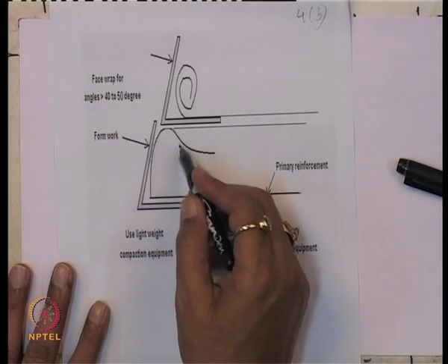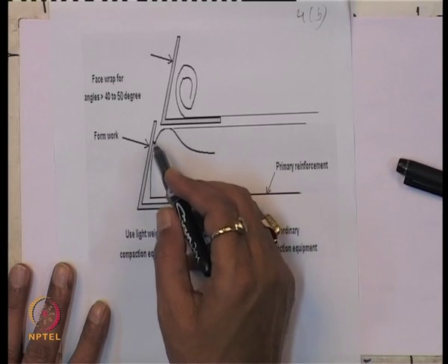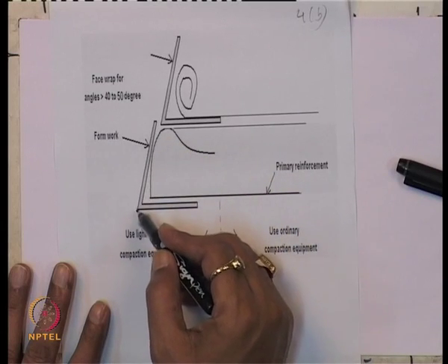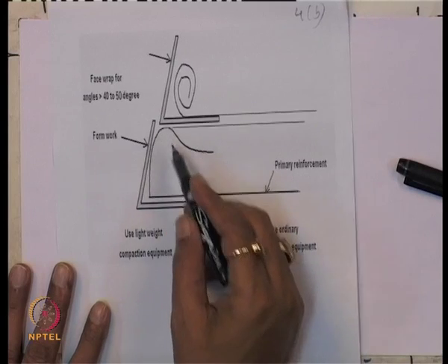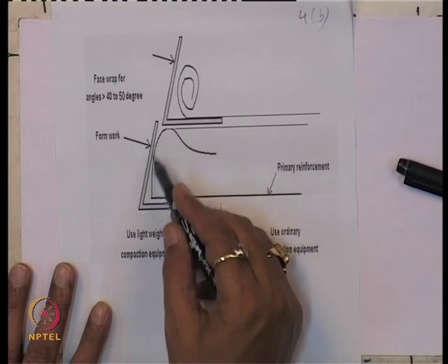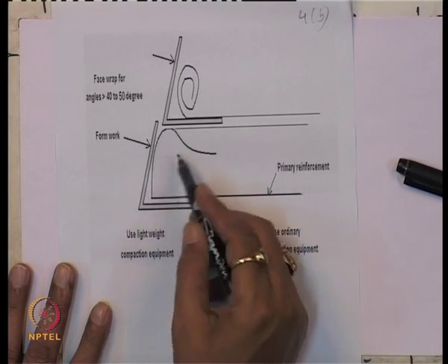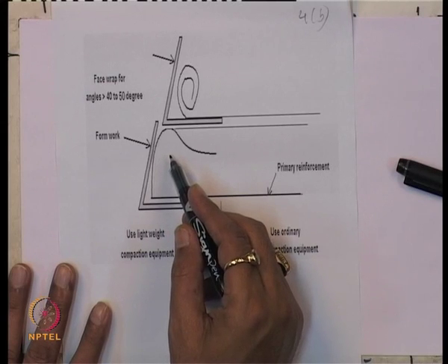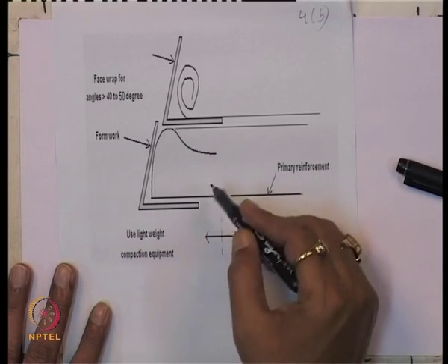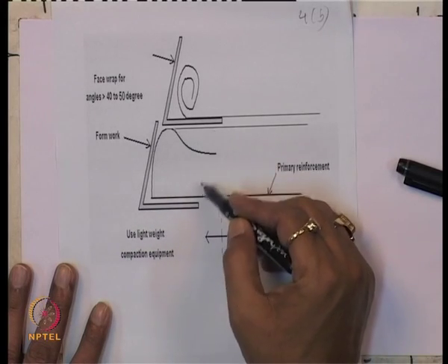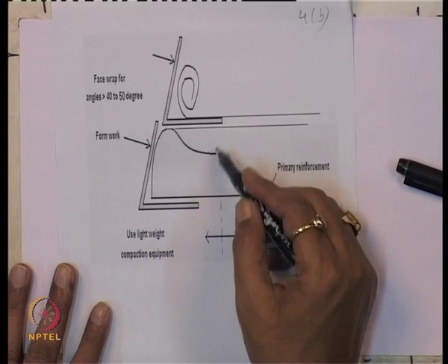So, this is wrapping around you are doing, but a formwork is to be placed to support the steep slope face during the construction. And then this lift thickness is generally considered about 500 millimeter to 600 millimeter.